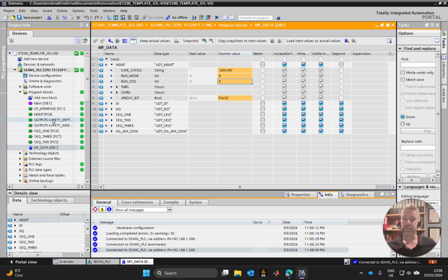And then after that, again, if you're using my template way here and you have a CP interface, what you'll do is you'll tie everything together using the UDT. So that's it. So with this PLC template that we have now, if you are in automation or mechatronics in UK WorldSkills and in what is going to be 5.5 weeks, so maybe 6 weeks, you are faced with a regional qualifier for UK finals and you're badly stuck for task C, or you're looking for a quicker, maybe different way of coding your PLC, maybe this template could present a viable option for you.